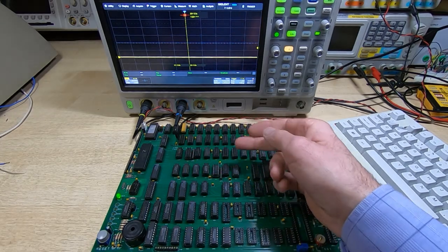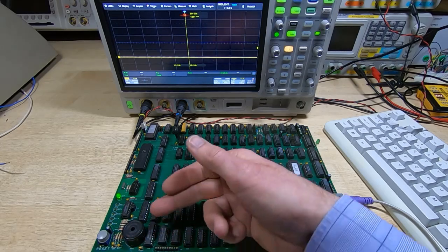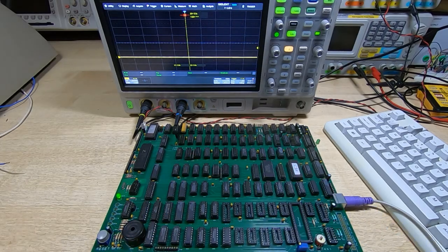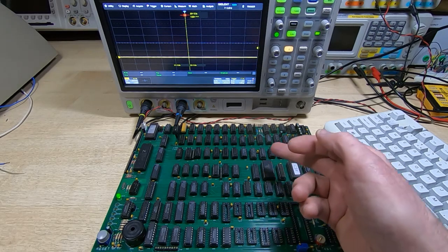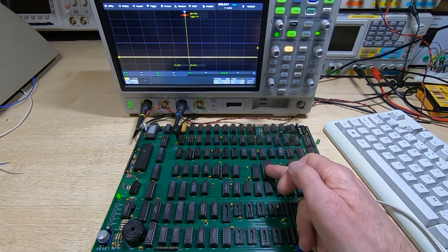The buffering appears to be working as it should, because all the things we looked at so far are on 3 separate data buses. And for them to work, they all have to work correctly, of course, because if they're not being properly selected, we won't get the correct data. So the video, for example, the fact it's changing at all means that the Z80 is capable of writing to the video SRAM.